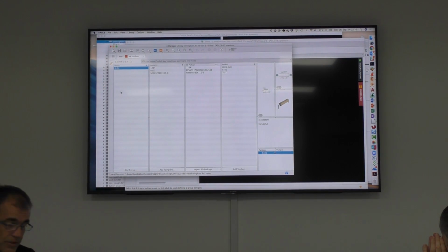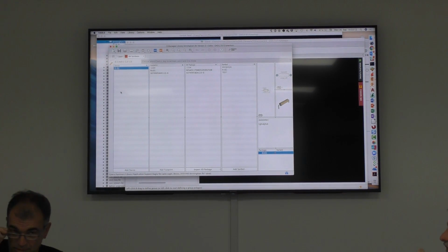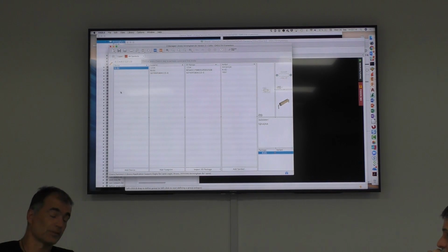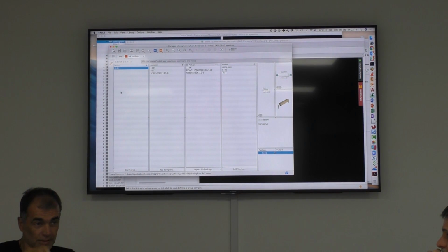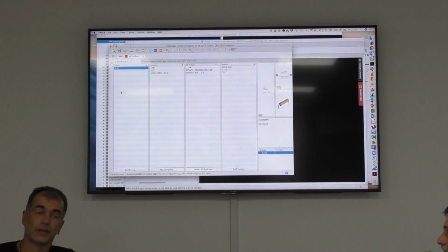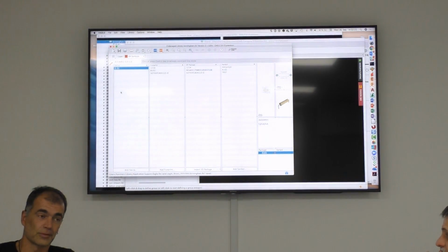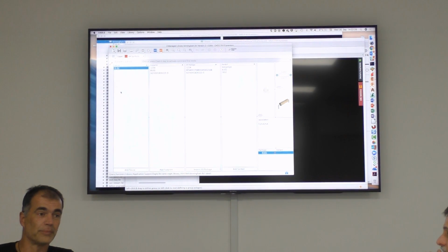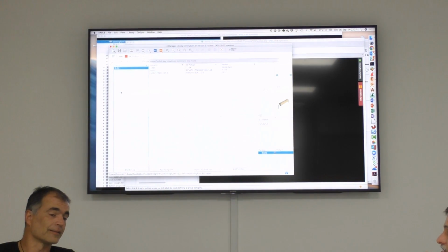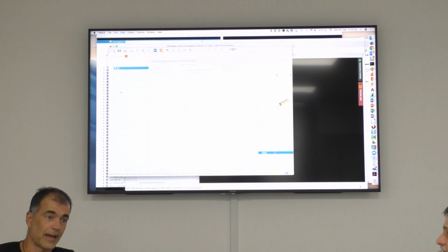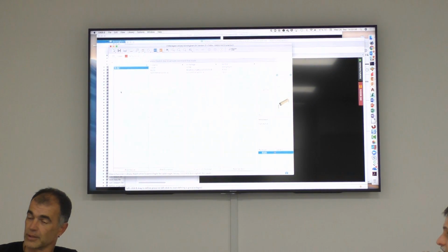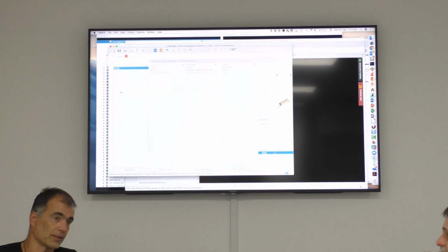So basically we finished the library design. What you have to keep in mind is as soon as you start dealing with 3D packages, make your library a managed library, and don't miss to do this. Then you can edit all the already existing footprints and get a 3D model assigned. The first step is a block, and then you can decide what to do.